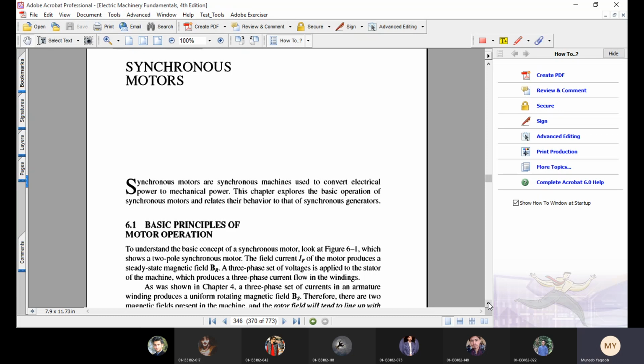So in even a simple application of a lift, we need variable speed. Due to this reason, synchronous machines are not very famous as motors. They are not very user friendly because they run at a constant speed, and in most of our applications, we need variable speed. In industry, three-phase induction motors are the most widely used motors.